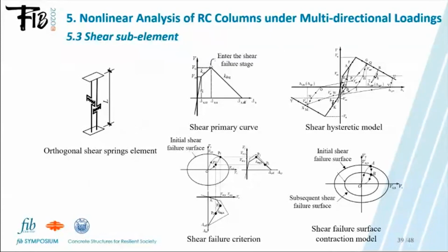The proposed shear hysteretic model, as introduced before, is applied here as the shear sub-element. In the multi-shear springs model, the uniaxial shear spring and the flexure sub-element are connected in series. Both sub-elements have the same force, equal to the external lateral loading. Lateral deformation is the sum of flexure and shear deformation, calculated by the flexure and the shear sub-element respectively.